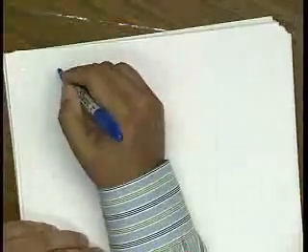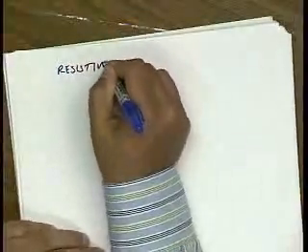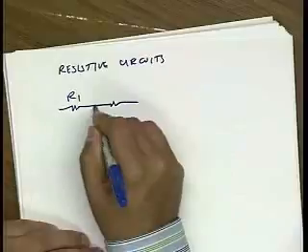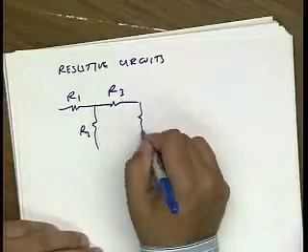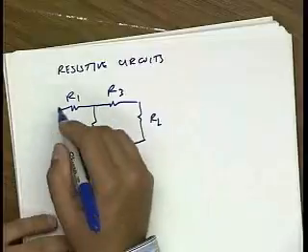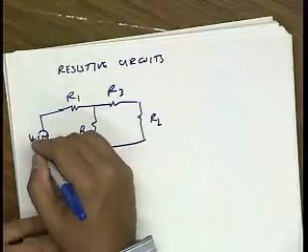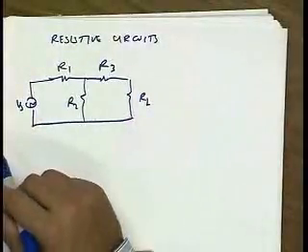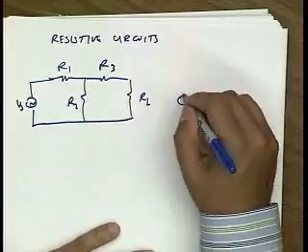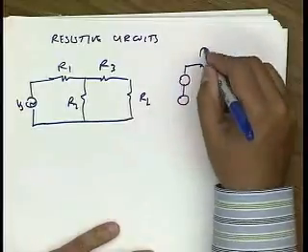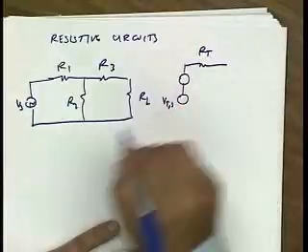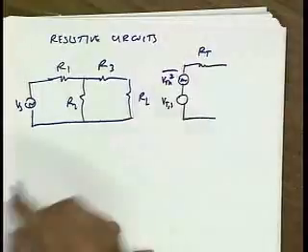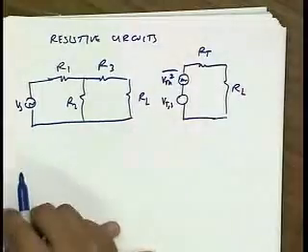Okay, more complicated circuits, let's just say resistive circuits. Let me say I have a circuit that looks something like this: R1, R2, R3, RL, and I want to find basically the total noise voltage appearing across this resistor RL. Well, I can use circuit theory and make this a Thevenin equivalent VTS and an equivalent Thevenin equivalent noise and solve the problem. Okay?